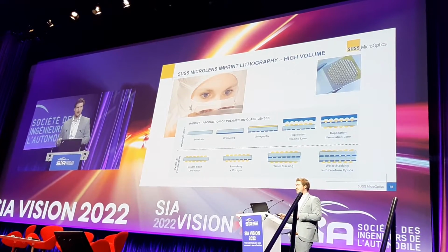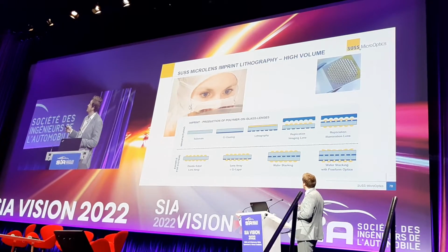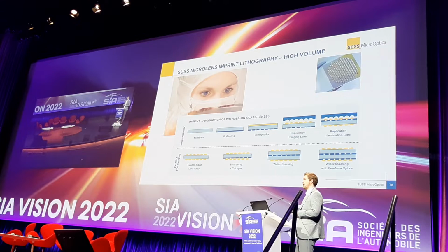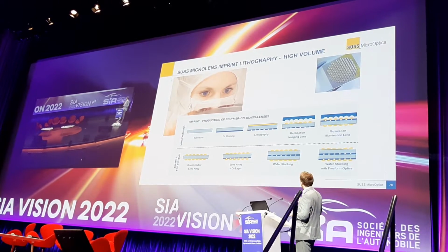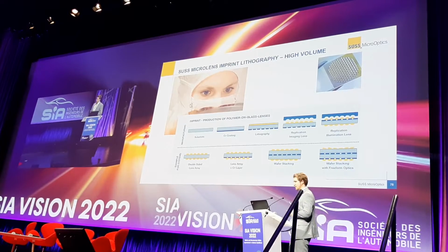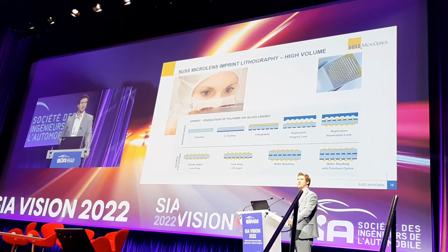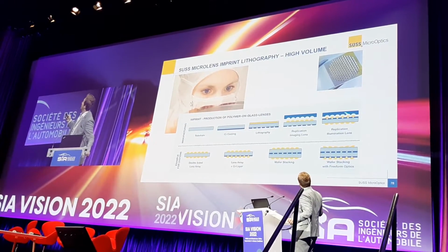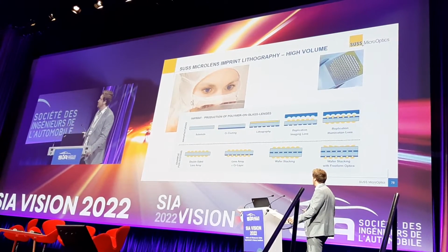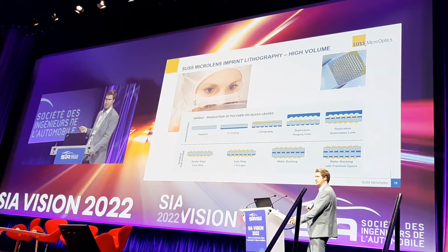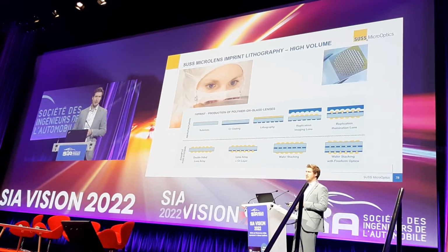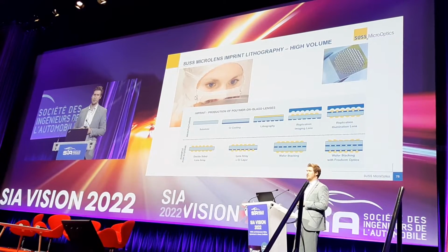And on the other side, the polymer is applied, and on this polymer a stamp goes down, forming the micro lenses, and then it's flipped around, and on the other side there will also be micro lenses made with the stamp. You can use these tools to make different designs. So this is the light carpet design that we usually have. We have the lens array, the chromium layer, then the substrate, and on the other side the projection lenses.